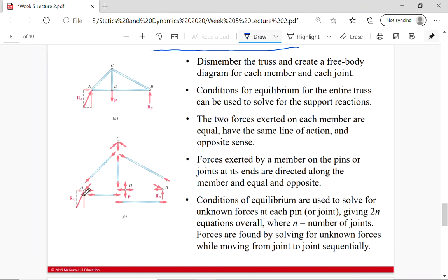Okay, so I would end up with forces at A, in this case due to this reaction force, which I could think of as X and Y components. But I'd also have the force from member AC, so it would be pointing here onto AC, but that meant at point A it would be acting the opposite way. Similarly member AD, if I assumed it was pulling this way, would have been reacting the opposite way at A.